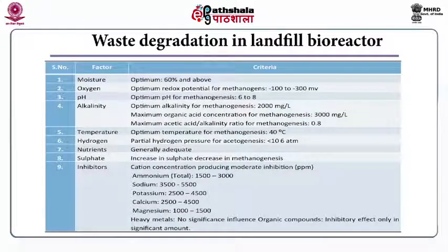Now, this table provides a summary of the conditions that should be maintained for better degradation within a landfill bioreactor. The moisture content should be maintained at 60% and above. The optimum redox potential should be around -100 to -300 millivolts, and this is favorable for the growth of methanogens. pH should be in the range of 6 to 8. Alkalinity, especially for methanogenesis, is around 2000 milligram per liter, and the maximum organic acid concentration during methanogenesis is 3000 milligram per liter.